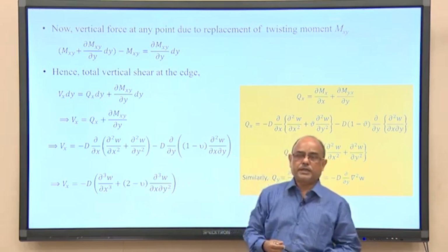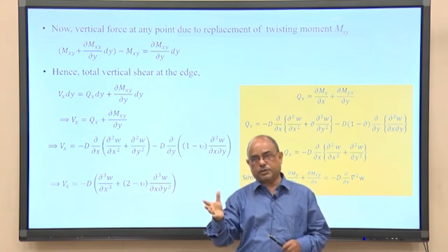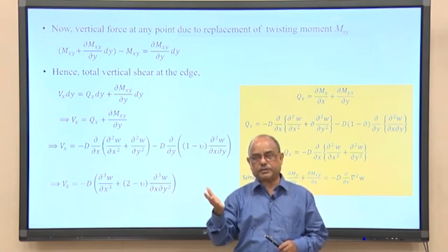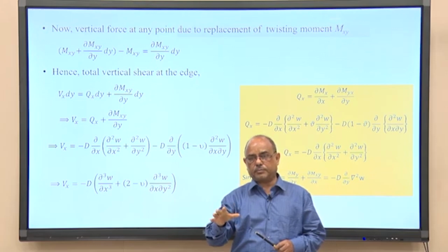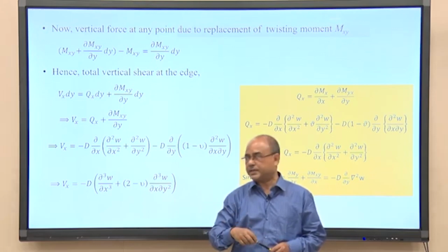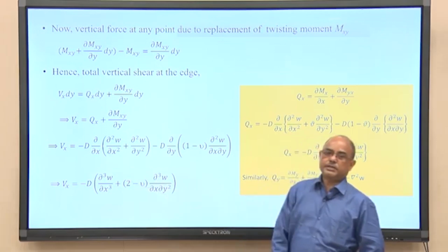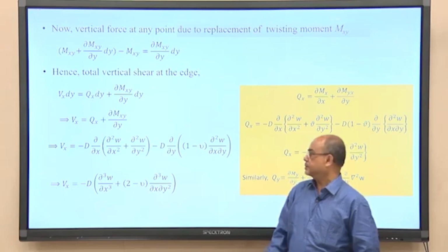expression for V x in terms of deflection, because we will solve the equation of deflection. The plate equation is expressed in terms of deflection, the generic equation. So, we will find the solution in terms of deflection, which is a function of x and y. Therefore, let us express the S shear in terms of deflection.